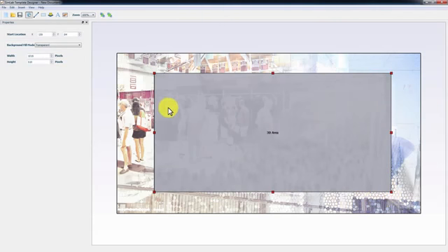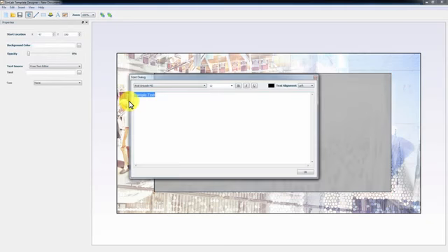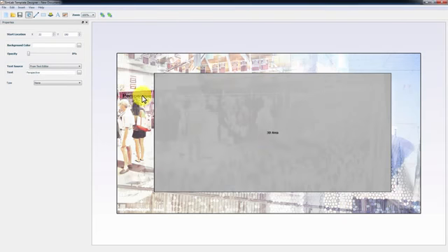Let us create buttons to view the scene states created earlier in SimLab Composer. Click on Add Text. Name it Perspective. I will add an image that resembles a sketchy button.